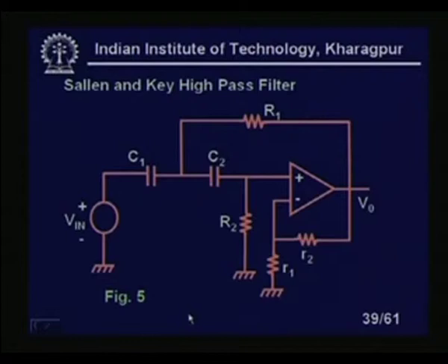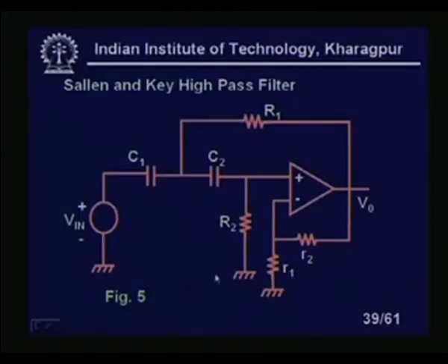So, it is fixed. Now, this is a high pass filter, you can see we have interchanged resistances and capacitances, right. So, if you interchange the resistance and capacitance, I will get a high pass filter. You can see this is a very handy circuit. If I know the design equations, I can make my own filter. It does not cost much, not more than 5-6 rupees. Only the op-amp is costly, the resistance and capacitance can be ordinary, right. But we need a certain amount of tuning.